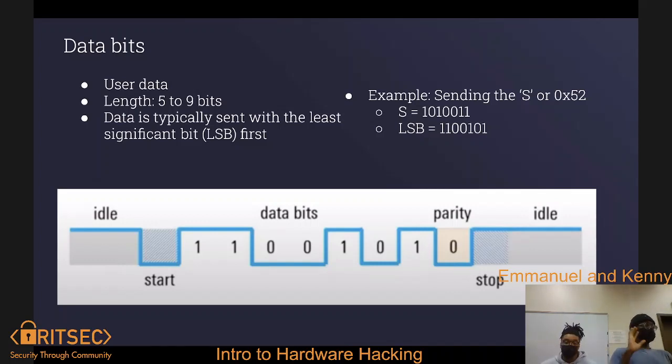Before it sends it, it has to flip the binary, so it becomes 11000100, whatever. As you can see in the image, it just sends that over. The other device, if it's listening on the same rate, would be able to convert each data byte to ASCII characters for us to see. This is one of the straightforward parts of the UART frame.